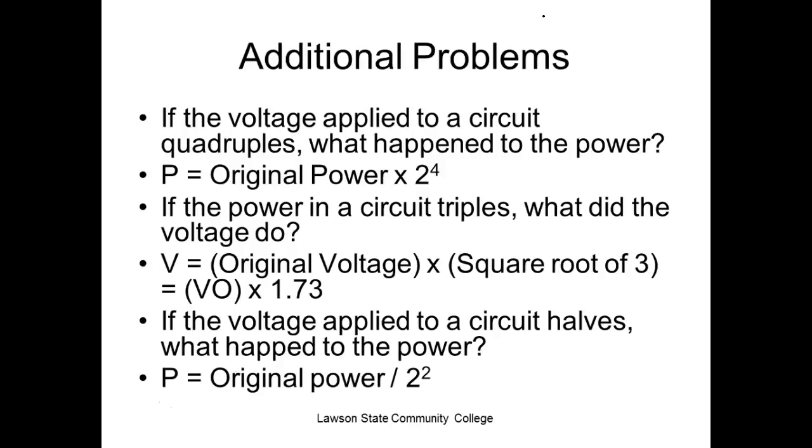But you understand now, so all you're doing, remember it's dB. So if I put 2, it would be squared. But if I use 20, then we're converting to dB, right? The current formula would be the same. It would be 20 log I out over I in, but we very seldom use that because what do we have to do with current?